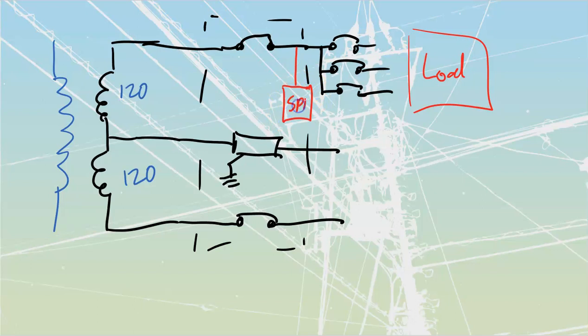We'll cover how they're made later on, but let's just take a look at what that SPD is going to do. Most of our SPDs are going to go across from line over to ground. Now, we don't necessarily see that they're just connected line over to ground. What we usually see is that they're going to be 3-wire. What they're trying to do with that 3-wire, the one neutral wire that's going to be part of the component, is connect this thing back to the bond, which is then in turn going to be connected to ground.